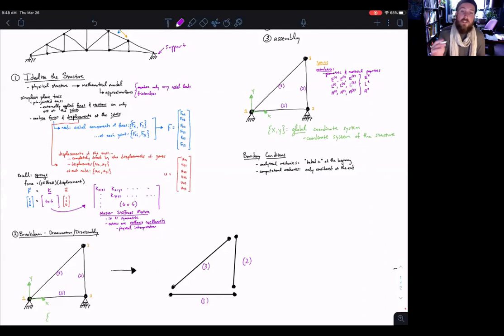Once we have the stiffness matrix, every entry of K in that 6x6 matrix, and we're ready to solve the problem, we're going to impose some force, and we're going to say at node 3 have a force of some value, and then we're going to have to tell it, in order to solve this equation, to restrict the degrees of freedom.